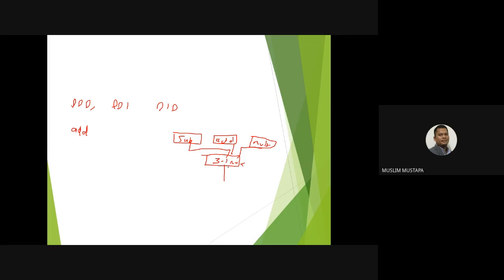So you have to know within the mux itself which one is which. Let's say you have 3 inputs, so you need to have at least 2 bits: 00, 01, and also 10, right? If you want to do addition at this counter, what's the signal that you have to send to the mux? Let's say this is your mux control. Your mux control is equal to addition, so it's 01.